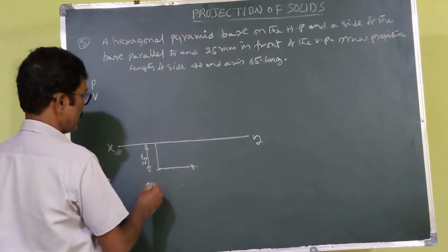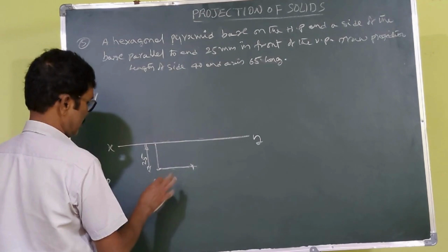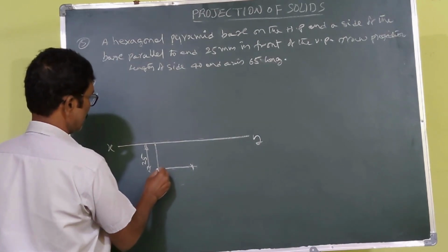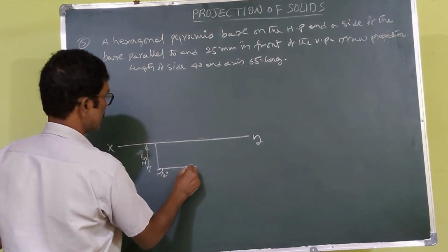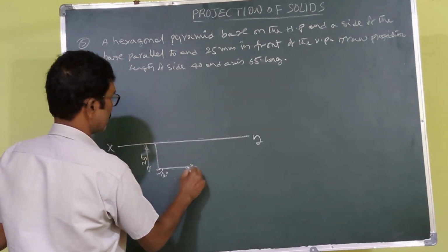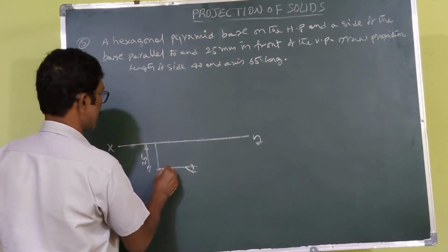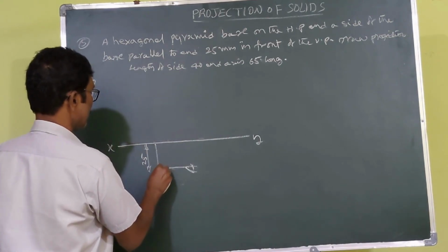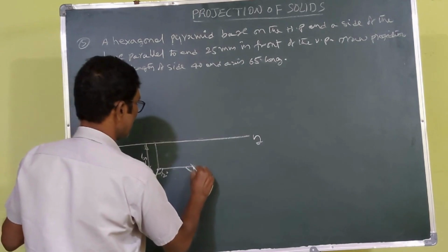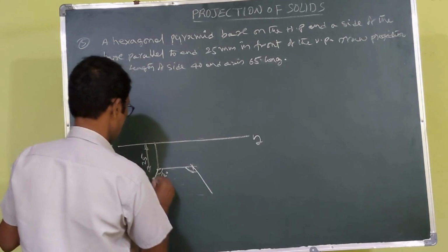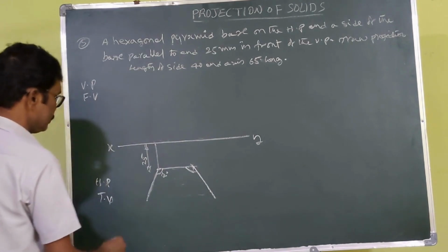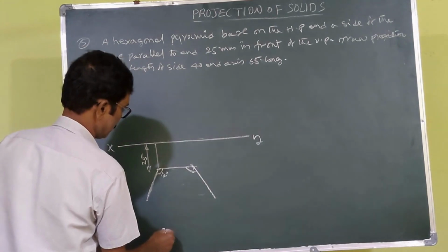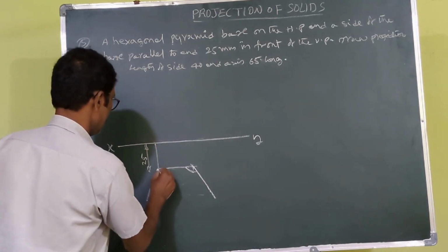Okay, here you have to construct the hexagon. You know how to construct the hexagon. You put 120 degrees here, 120 degrees here, and you put 120 degrees here also. This is the center. You draw the line. You draw the line here also, and again simple construction.